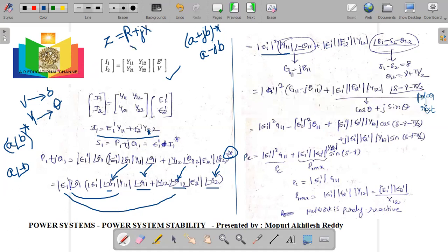Similarly, when we had an admittance, Y is the inverse of Z. So Y can be written as the real part of Y, the inverse of resistance, that is conductance G, plus j times the inverse of reactance, that is susceptance B. So Y can be written as G plus jB when we are converting it from polar form to rectangular form. See, this is actually polar form. Now I am converting this polar form into rectangular form.